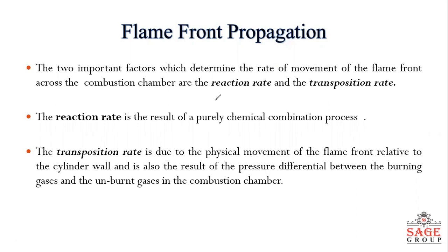The first one is the reaction rate, which is a purely chemical combination process in which the flame eats its way into the unburnt charge. So whatever burning charge is there, it will mix with unburnt particles and the flame will spread. Then there is a transposition rate. It is due to the physical movement of flame front relative to the cylinder wall, and also because of the pressure differential between the burning gases and unburned gases present in the combustion chamber.